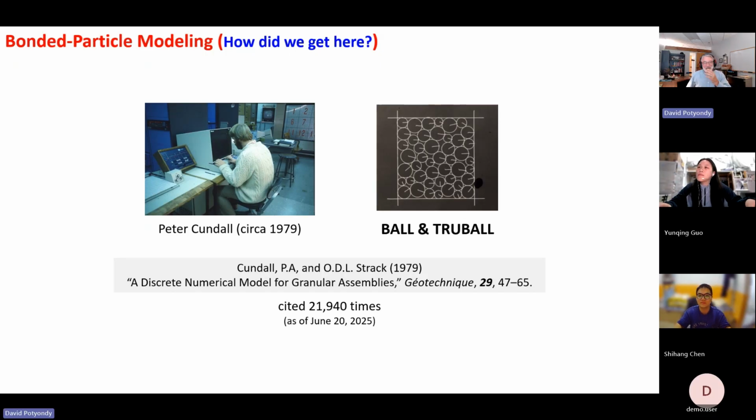If it was a 2D model, you could visualize rotation very easily, and quantify it by just measuring the angle relative to the horizontal. You could monitor and sum up the rotation in radians, because every time step the particle has a rotation velocity and a translation velocity.